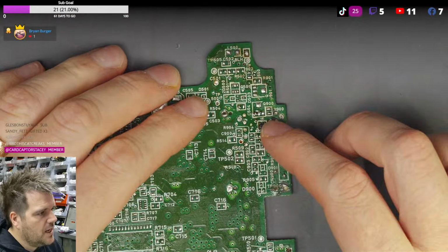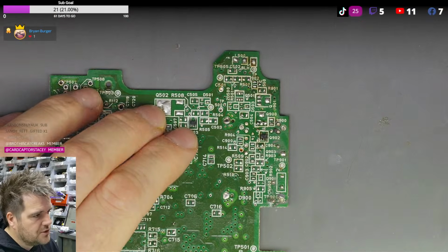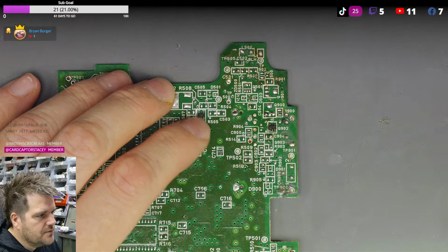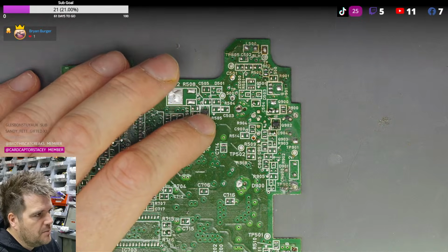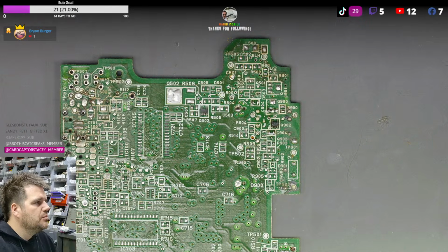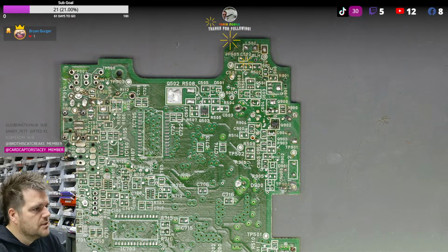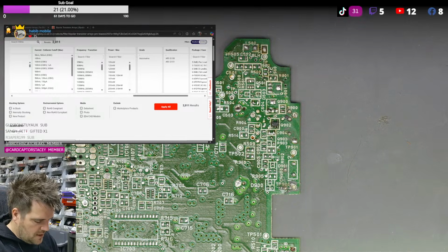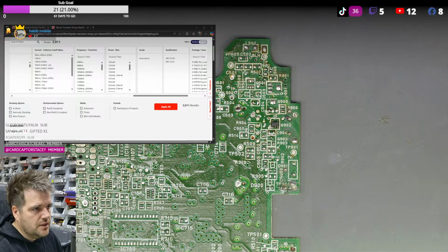So you have now a package that's got 5 pins. It's clearly a SOT package. It's 5 pins, and we've got a pitch of 1mm. So from there, I will pull up the internet, and I will basically type in, I'm going to guess, firstly, a SOT23-5 package footprint.